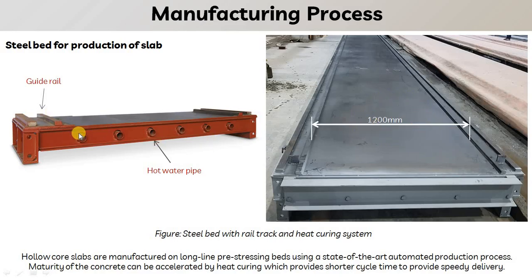It has a guide rail on both ends to run the machine on, and we have the hot water pipes below the bed, which are used as a curing system, which will enhance the strength of the concrete and give the early strength of the concrete. So this system is known as the steam curing system.